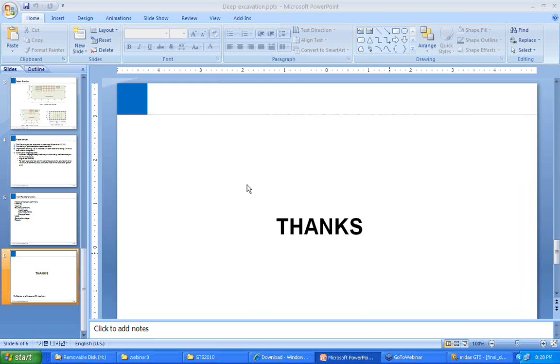If it's curved, the only criteria you follow is you have the local axis, and all the axes are aligned along the local axis of the tunnel. So if you have three perpendicularly aligned tunnels, you check for the results for mxx or myy separately for each tunnel. You have separate coordinate systems for each of them, which I will be focusing on in my coming educational webinar on tunneling. And then you align all the coordinate systems in such a way that the x-axes are aligned with the local axis of the tunnel.